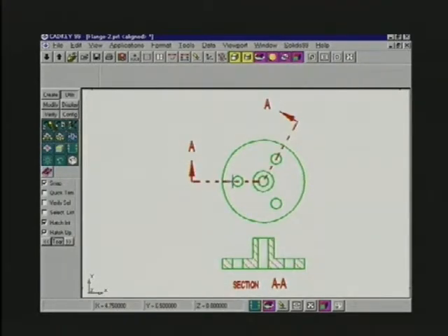However, you'll notice that the cutting plane has a bend in it, and we pretend that we've aligned that second hole, that we've swung it around till it's straight across, and we didn't project straight down to project a warped thing, but we've aligned the features before we place them in this section view. So here you see an example of an aligned section view, very commonly used when we have objects that are symmetrical about an axis of revolution.